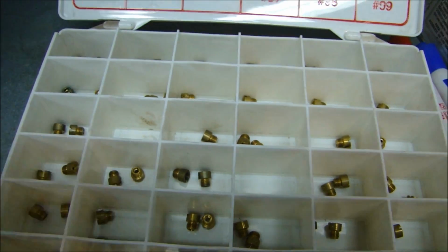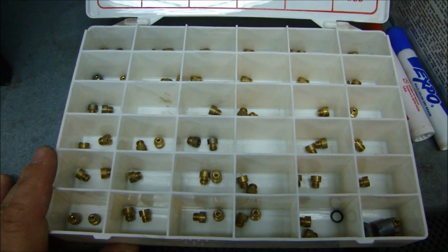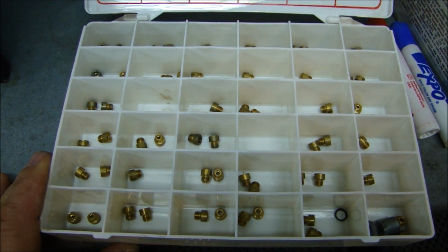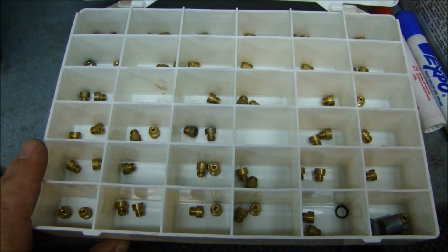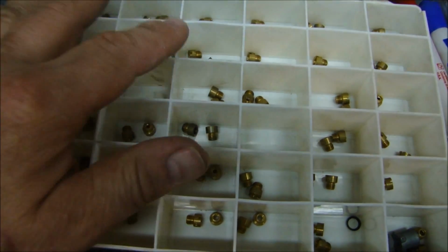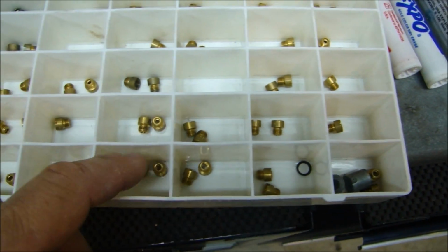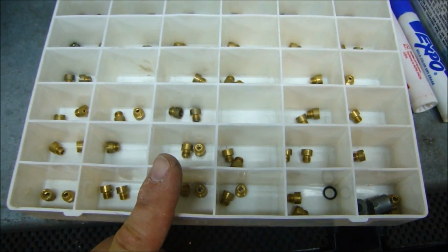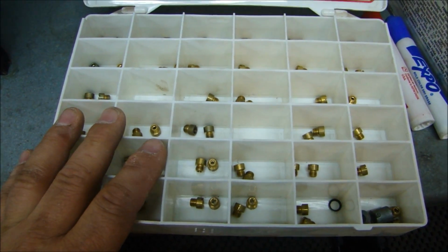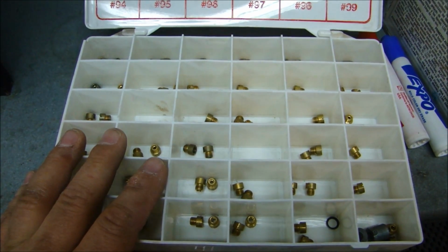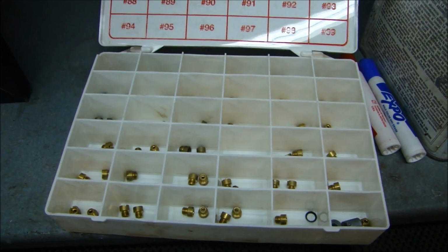So when you adjust your engine and you have your vacuum gauge installed and you're going down the street at wide open throttle and max RPM, and you don't have enough vacuum, it means you're not metering the fuel properly. You can rejet the carburetor and change the jets inside to make sure the fuel is being metered properly. I'm not going to get into that in this video because this is about choosing a carburetor, not how to adjust it. That video would be very long, but that's why you want to team up with a dyno guy or someone who can help you do that part.